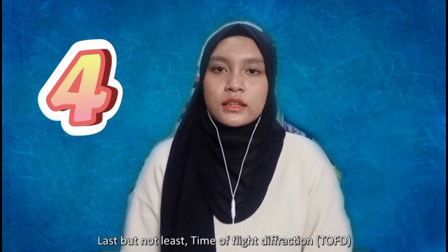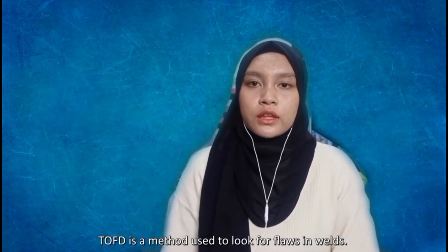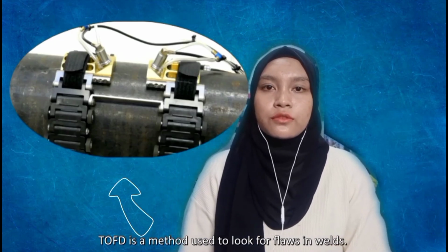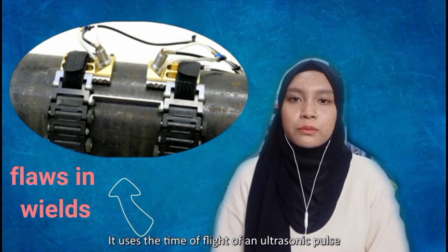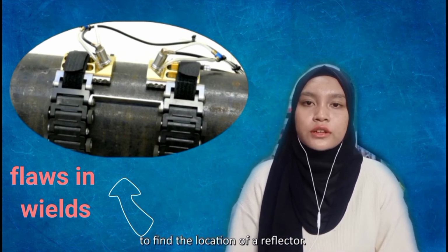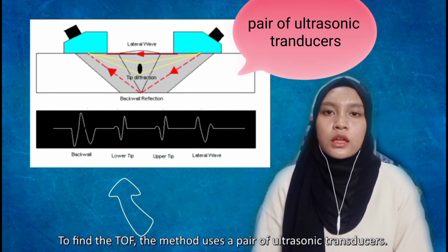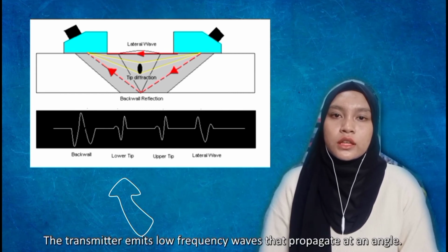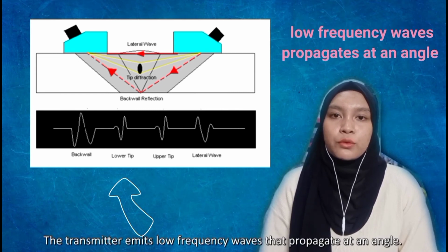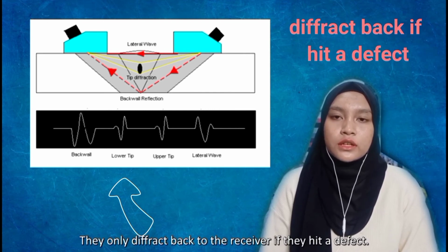Last but not least, time of flight diffraction, TOFD. TOFD is a method used to look for flaws in welds. It uses the time of flight of an ultrasonic pulse to find the location of a reflector. To find the time of flight, the method uses a pair of ultrasonic transducers. The transmitter emits low-frequency waves that propagate at an angle. They only diffract back to the receiver if they hit a defect.